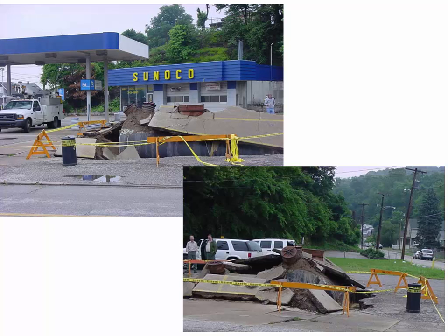And so down here, the soil voids are saturated, meaning that obviously soil is a mixture of solids and empty spaces. Underneath the water table, all of those empty spaces are full of water. So the soil is saturated. Above this, the soil is dry. And that's not quite that simple because even dry soil has some moisture that's attaching itself to the soil grains.